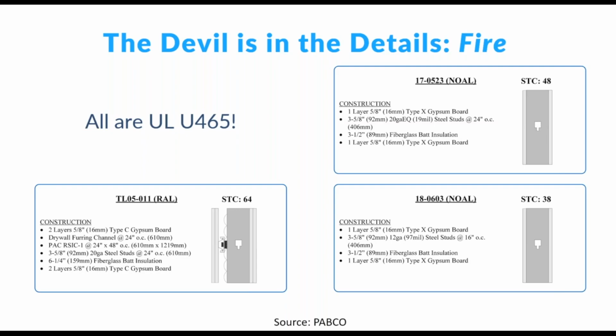So we need to pay attention to not just the details of the fire rated design, to make sure that we're following our UL design or what we're pulling out of the Gypsum Association Fire Resistance and Sound Control Design Manual, but we also need to pay attention to the elements that affect acoustics. And we'll go in and talk more about some of those. But layers of gypsum board, isolation, stud thickness, spacing, all of those things do matter.